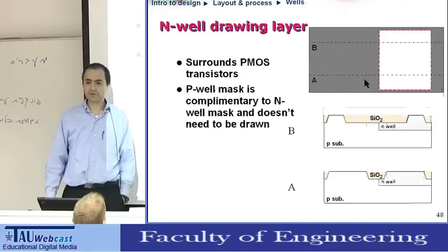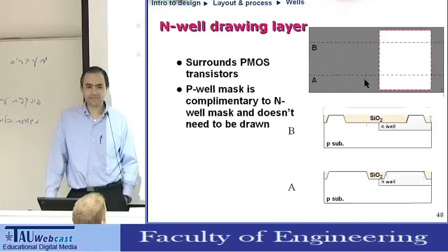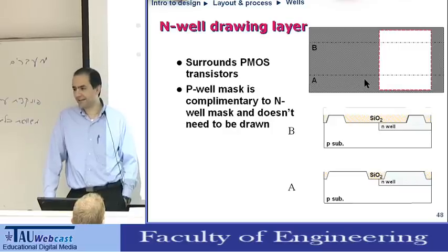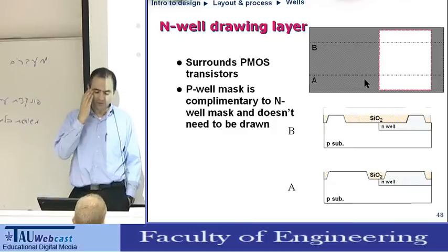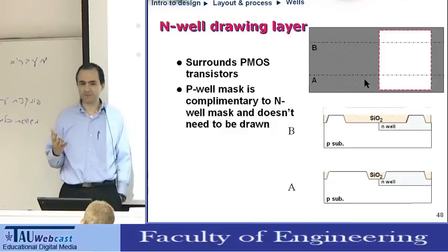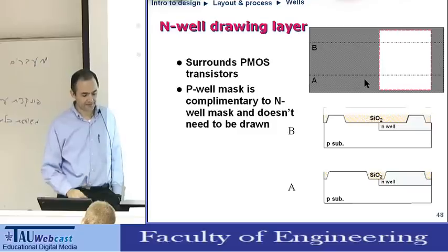Okay, so which resolution will we choose here? This is several microns across. So still, we can do it with visible light, but we will still use I-line. There's no tool with visible light anymore in the fabrication facilities.